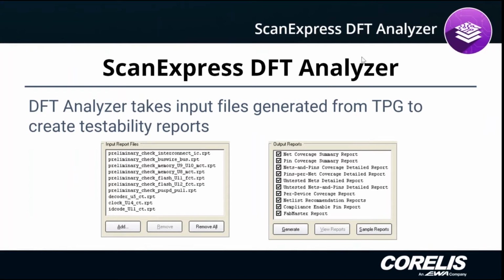So ScanExpress DFT Analyzer takes input files that ScanExpress TPG is going to create and creates testability reports. When we say testability reports, we're saying it's going to tell you what kind of open and short type coverage you will get based on the test that you've generated.